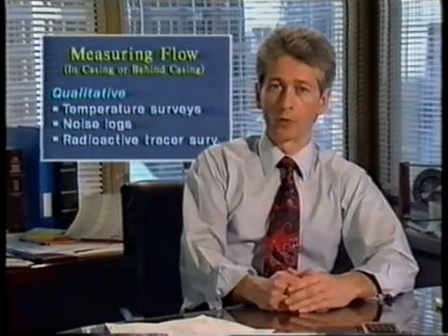In this unit, we look at the techniques for measuring flow in or behind casing. These techniques can be qualitative or quantitative. The basic qualitative measurements used to evaluate fluid movement include temperature surveys, noise logs, and radioactive tracer surveys. Quantitative techniques also include radioactive tracers, but most commonly rely on flow meters or the newly developed oxygen activation log. First, let's investigate the qualitative devices.